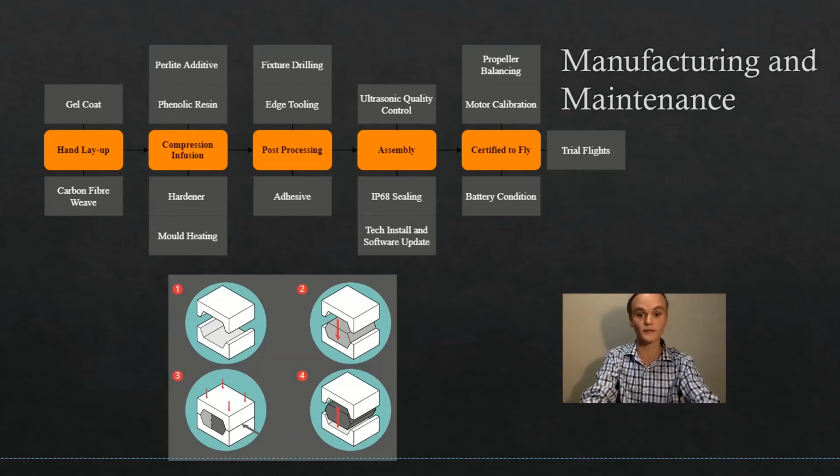Compression molding was then selected as the final manufacturing method. Several factors make this the most viable option and are addressed by their weighting in the project constraints for manufacturing cost, sustainability, and robustness. The storage logistics of keeping resin, hardener, and fibre separate is much simpler than preventing prepreg materials from degenerating. Intensive power requirements for autoclaving were avoided by implementing curing inside the clamp molds.